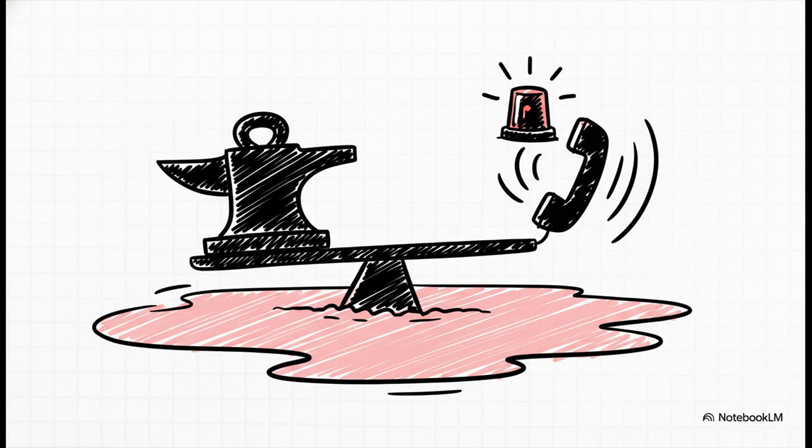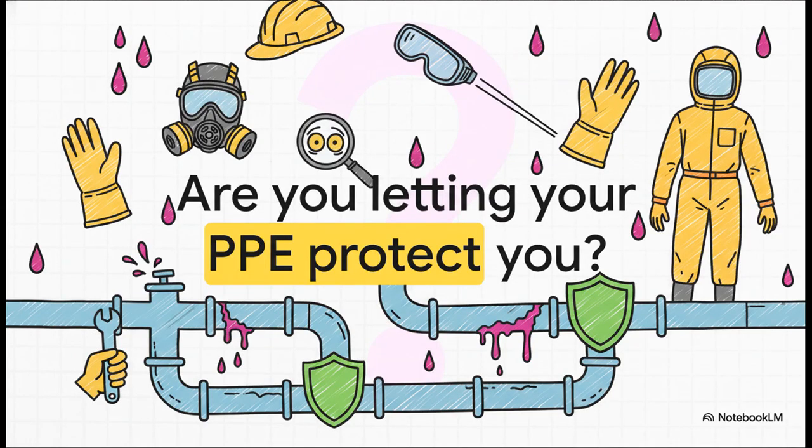Finally, regarding environmental emergencies, if a major spill occurs, your first priority is securing the area. The SDS advises diluting the spill with water and neutralizing it with sodium carbonate, that's soda ash, if it is safe for trained personnel to do so. However, you must be aware of the federal limits. Any release of potassium hydroxide over 1,000 pounds is the EPA reportable quantity and requires immediate notification to the National Response Center.